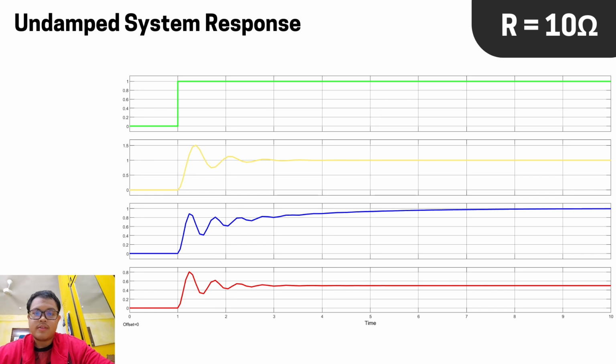All three different systems, the open loop system, the PID controller system, and the closed loop system, have the same rise time. But after the rise time, they have an overshoot, which will then oscillate until they get a stable value. For the open loop and closed loop system, both settling time and rise time are the same. However, we can see that in the closed loop system, the gain actually is half of what it used to be,